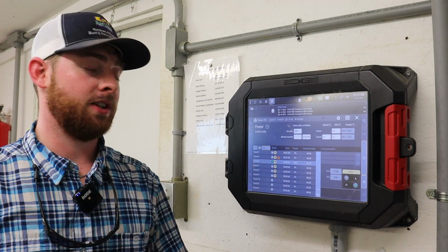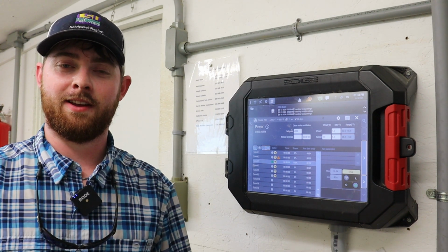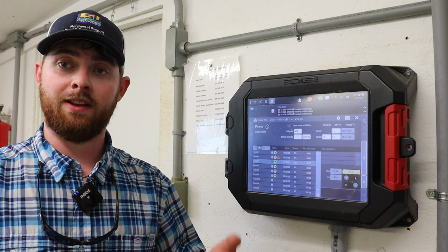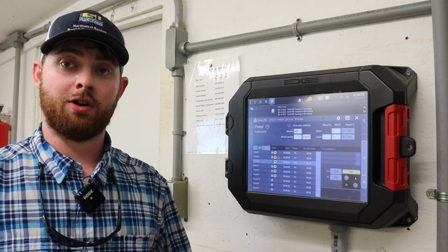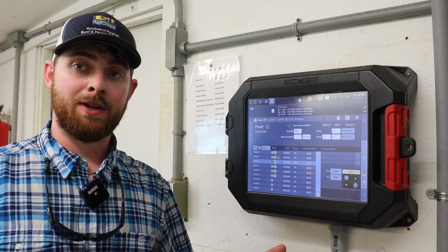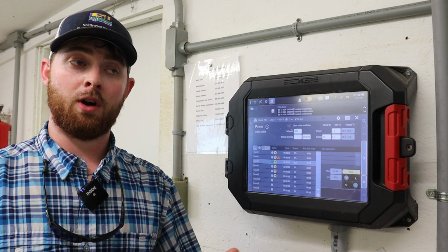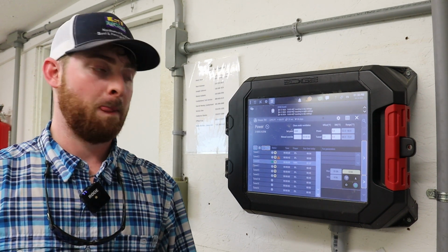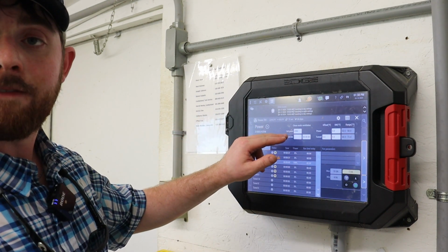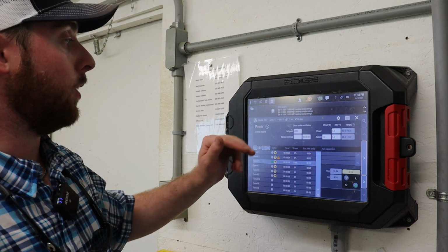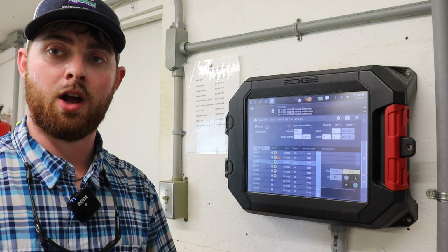So how do we conduct a house tightness test? Well, first you're going to want to pick a calm day, right? Wind can affect things. Then you're going to close up all of the inlets in your house, both tunnel and sidewall. And then finally, you're going to turn on a fan. How much depends on the configuration that you have. Usually one tunnel fan's enough, but we're shooting for about 1 CFM per square foot. So we have a fan on here, our inlets are closed up, and then finally we're going to read our static pressure, and we're pulling 21 points, or 0.21 inches of water column.